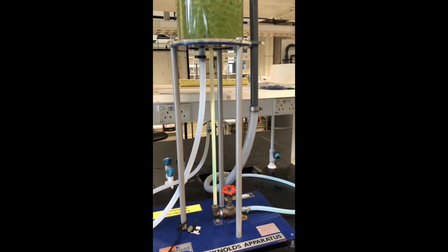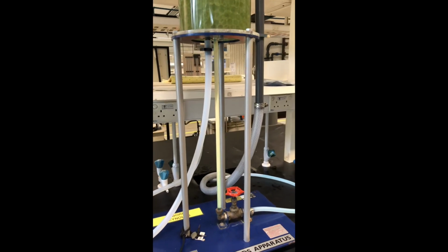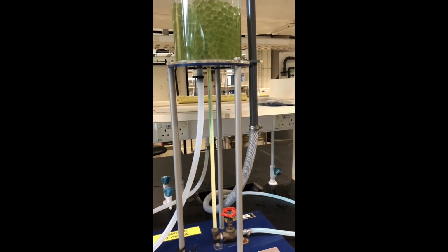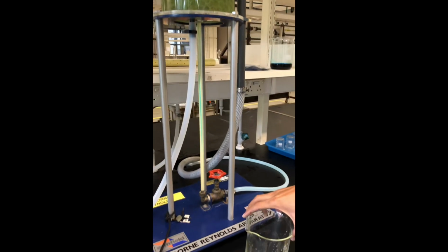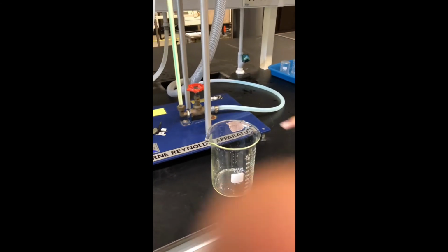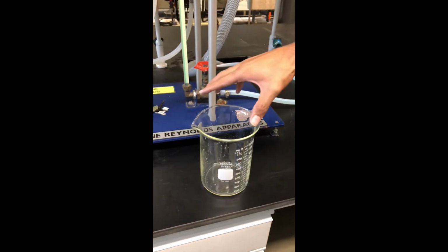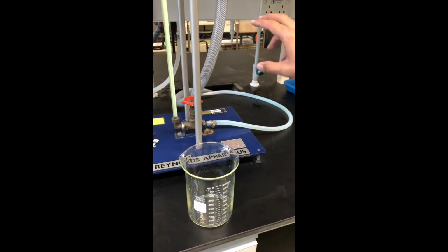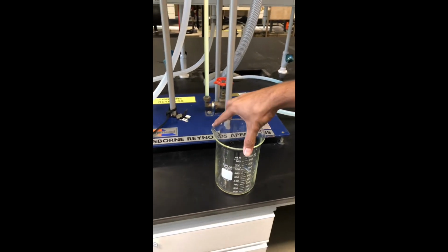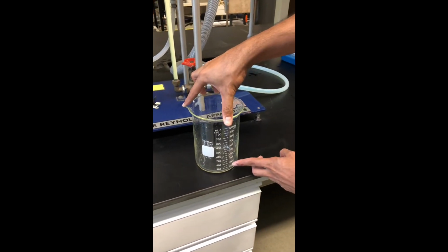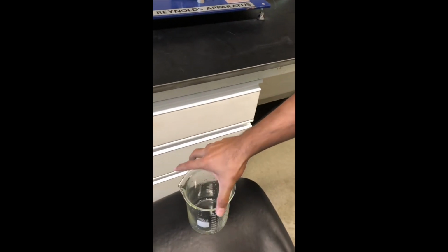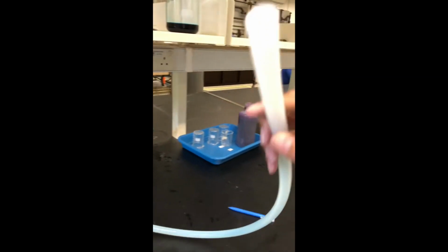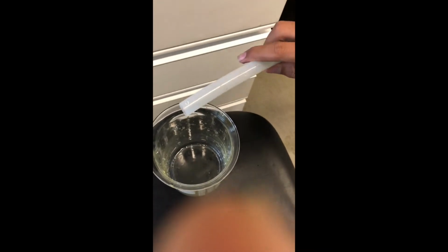Now, in order to take the readings, you will have to measure the time taken by the water that is coming out of the outlet pipe, which will be collected in a glass beaker such as this. In this test, we will be measuring till 100 ml of water, and we will measure the time it will take to fill 100 ml of water in this glass beaker. So let's take the outlet pipe out from the drain, and let's start the stopwatch.